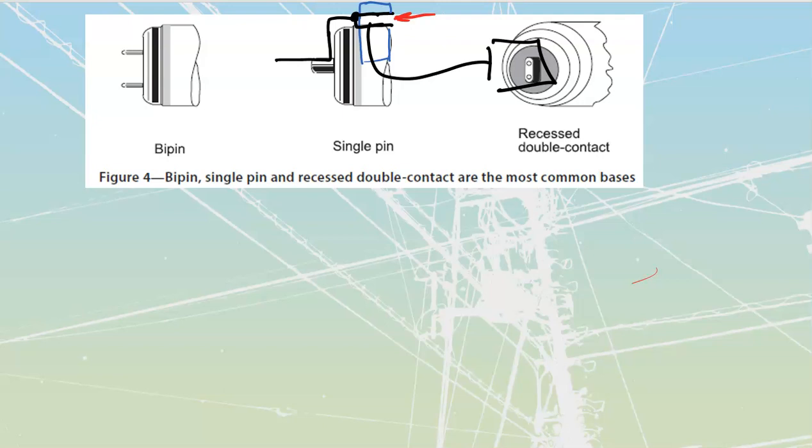This used to happen with some of our fluorescent lights that were operated directly off a system frequency, in other words, off that 60 hertz. And because motors and so many other moving pieces of equipment are also reliant upon their frequency, right? F is equal to P times N over 120. You remember that formula? That means that they're also going to be operating at the same frequency.